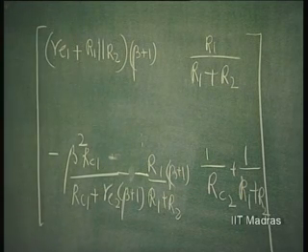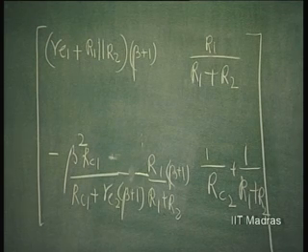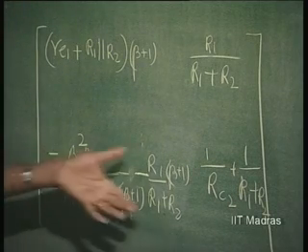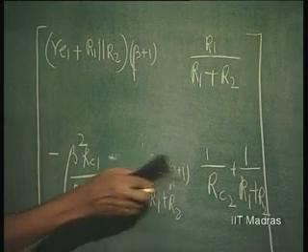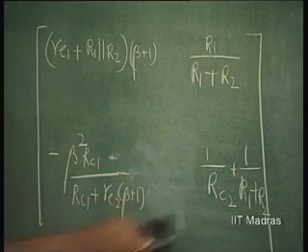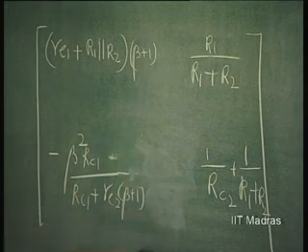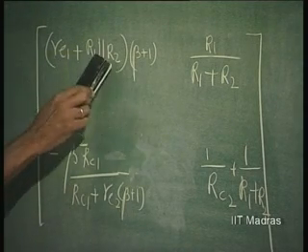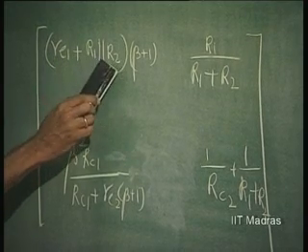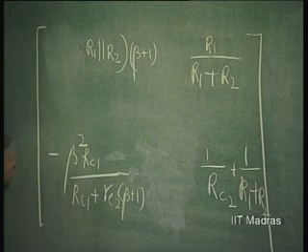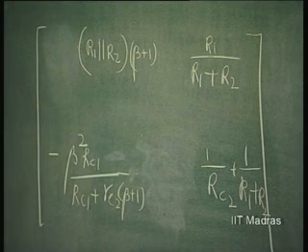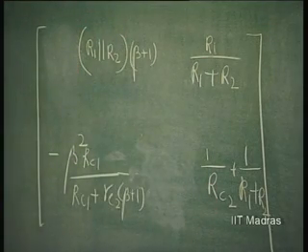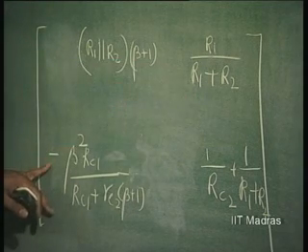So, the loop gain. Since this is beta squared here, this factor we are going to ignore, let us say this is neglected, very small, neglected because this is beta squared. Here all can become comparable except Re1 here, which is very small compared to R1 parallel R2 normally. So we have simplified these parameters now. These parameters will establish the loop gain as negative here. So this is negative feedback.